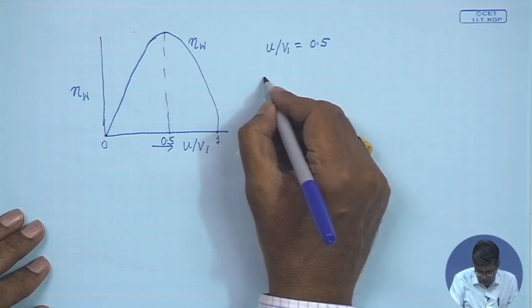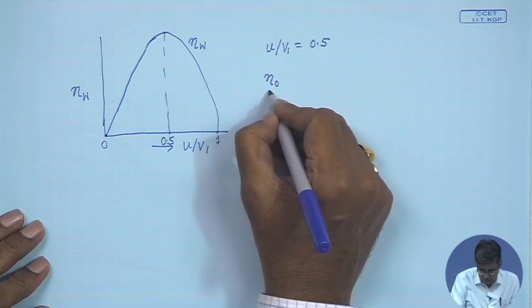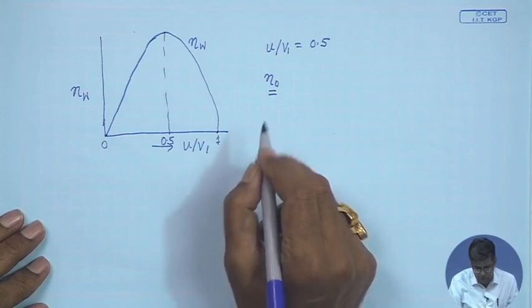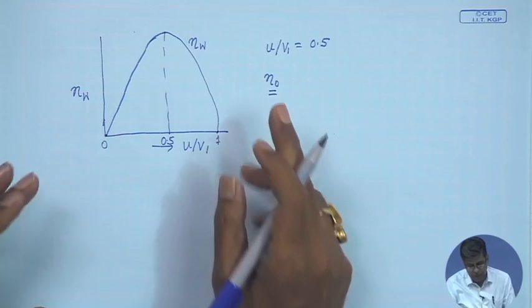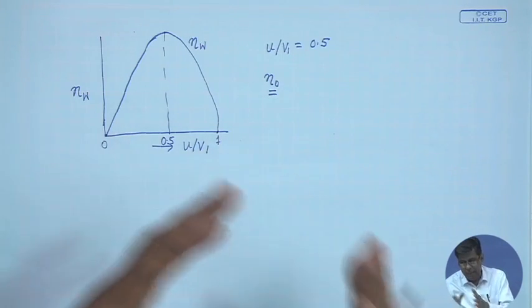But the overall efficiency, which is related to the power output at the final shaft at coupling, as I have already told in earlier classes, is always less than the wheel efficiency or hydraulic efficiency, whatever way you call it, because of the frictions in glands, bearings and couplings.